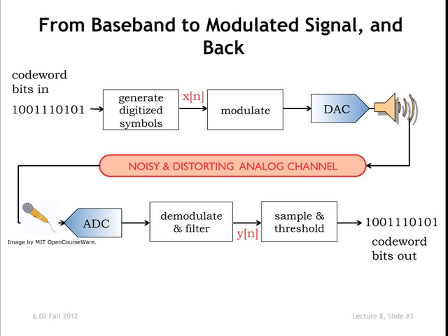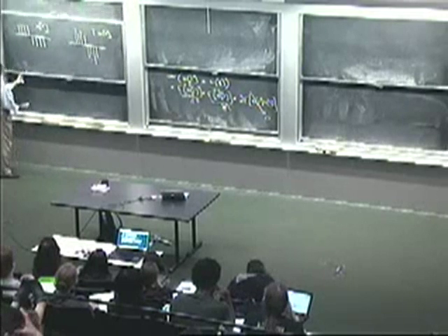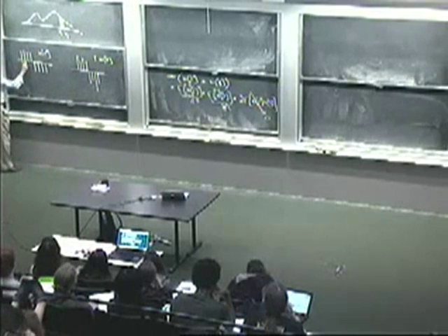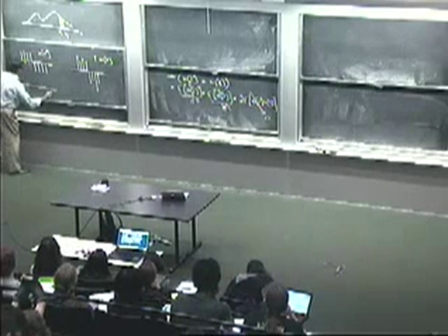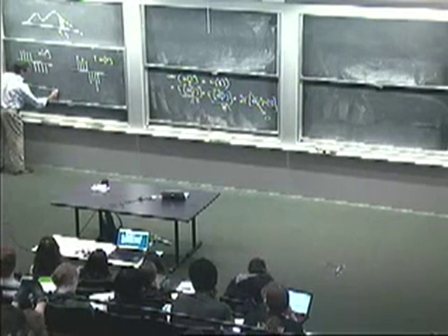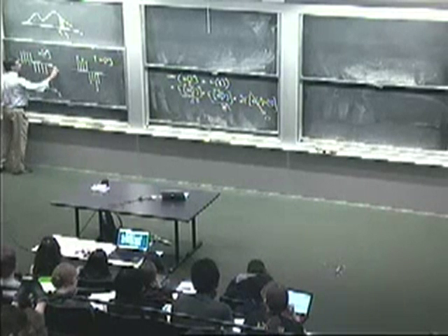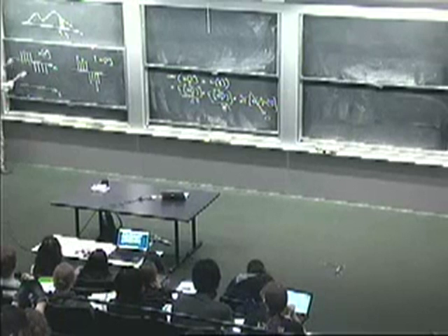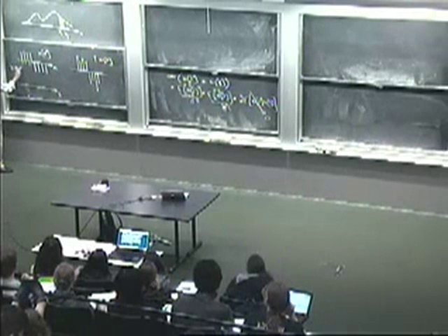So the challenge then is taking the digitized symbols there and putting them onto a physical channel. So what is it that happens in between? The D2A converter, we don't say much about that, but a typical D2A converter is taking a sequence of samples which are just numbered and then converting the samples to a continuous waveform, which is on a time axis. So a discrete time sequence is typically on an integer axis, but we convert it in a D2A converter.